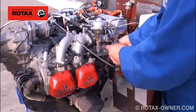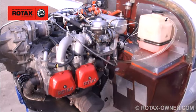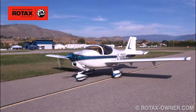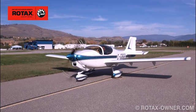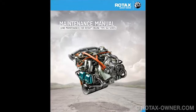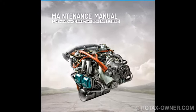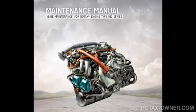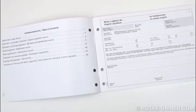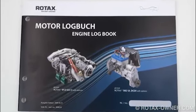After restoring the aircraft to its original operating configuration, conduct a test run. Refer to Chapter 12.20.00 of the 912-914 series Line Maintenance Manual, current edition. Finally, enter this mandatory service bulletin as complied with in the engine logbook.